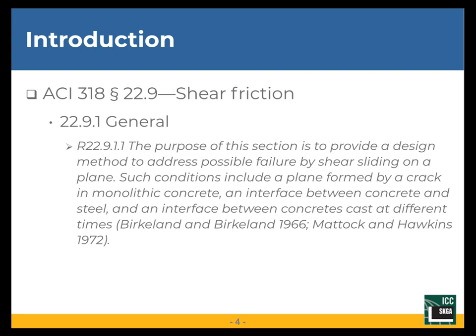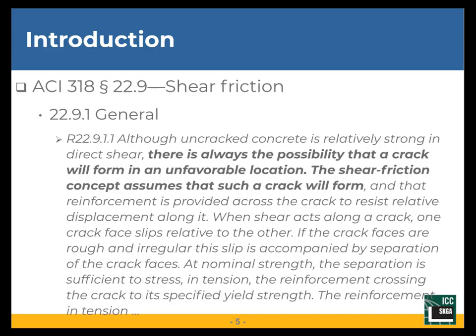Looking over on the commentary side, it gives a little more guidance. It's a method to address failure by shear sliding on a plane. When we're talking about shear friction, it's often an intentional plane, but that plane could also be formed by cracks in monolithic concrete. And then it talks about some of the early references.